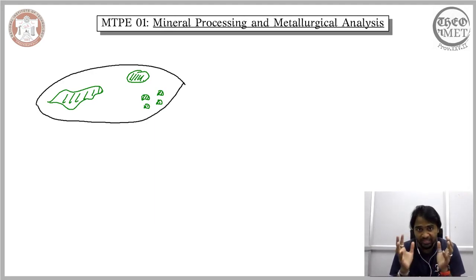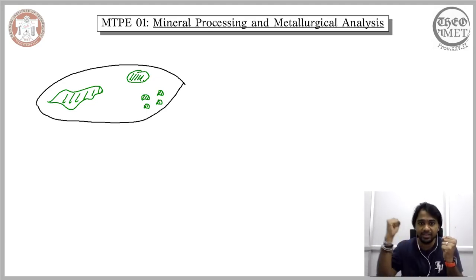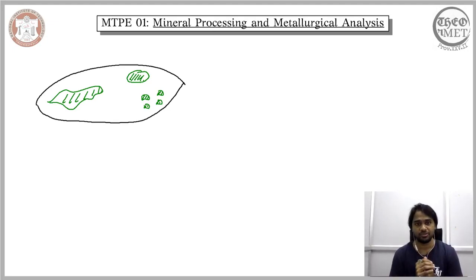The specific way is that we cannot directly reduce the larger particles into very fine particles, even though it might increase the degree of liberation. We cannot do that because that is expensive. So what we do is we separate the larger particles into tailings, middlings and the mineral particles, and then we subject only the middlings to the subsequent comminution. This way it is economically beneficial. This is something that we learned by considering the rather straightforward schematic particle wherein the mineral was centralized and located in a very restricted region.